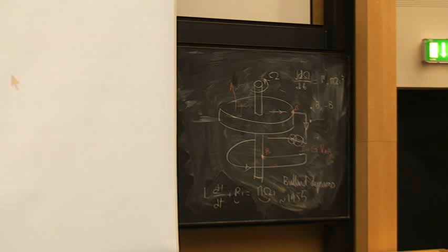Those field lines create a B theta. So what you do is you put the magnetometer here, you measure the value of B theta, and you use that to create the current that goes into the coil. Linear amplifier. The whole trick is the linear amplifier. It is one thing that makes it so hard, because any bias hurts you.